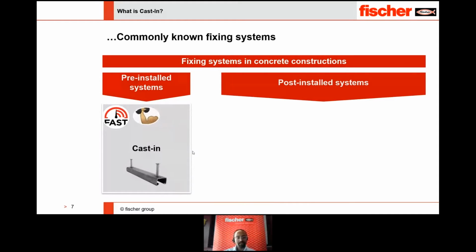It is heavy duty, it can take huge loads. It can resist corrosion because of the special coating applied on it. There is also no damaging of structural reinforcement bars inside concrete because you are keeping these cast-in channels before pouring of concrete, so you clearly know where the reinforcement bars are present, and you can adjust your cast-in channels to avoid any clashes.